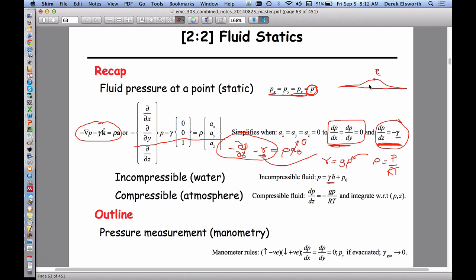The reason is that on the outside, where the pressure is atmospheric, we know the atmospheric pressure is about 100 kPa. And from what we know about pressures in the horizontal plane in any fluid being constant, the pressure here also has to be the atmospheric pressure, 100 kPa.